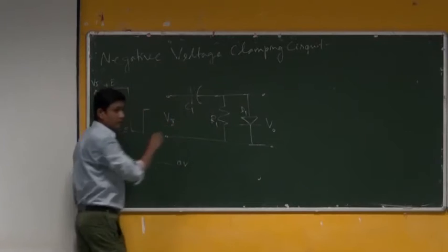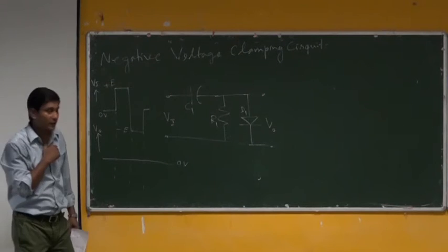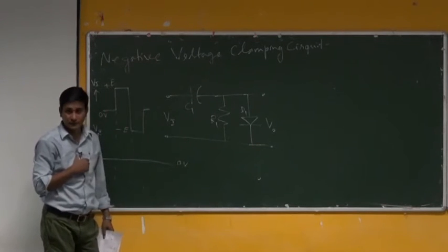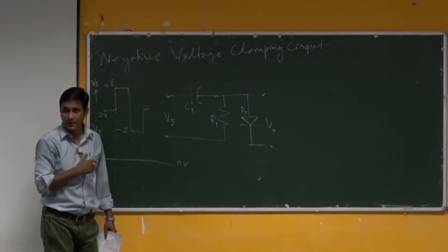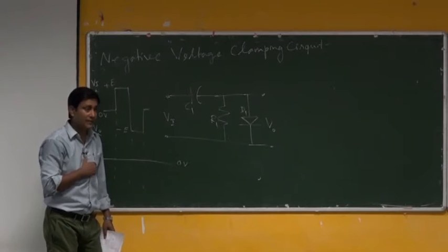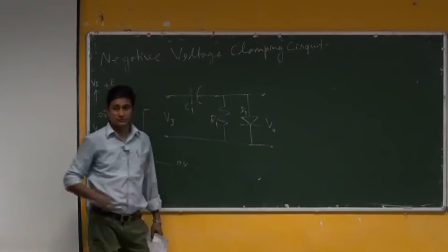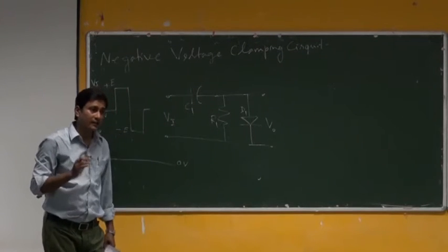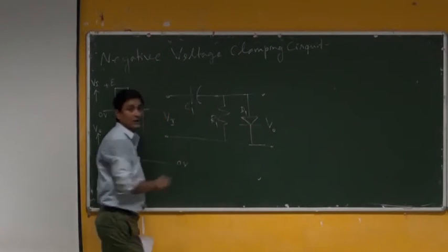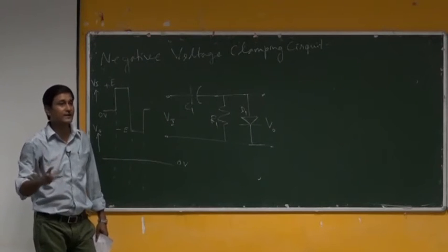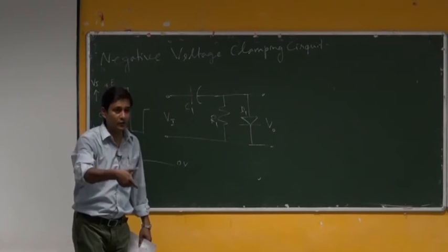This is the circuit arrangement which I need there. If you ask me why I have incorporated this resistor here, it may not be required because the capacitor alone is sufficient for the purpose of the circuitry we have implemented. Generally, sometimes we use the circuitry without this R1 also, but it is more practical to consider one resistor parallel to the output, because whenever you connect something there to collect that voltage, automatically one load will come into the picture.